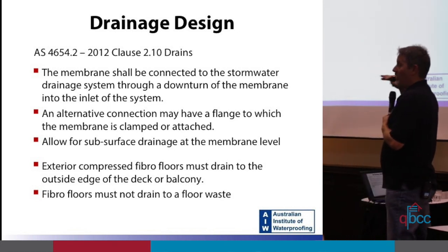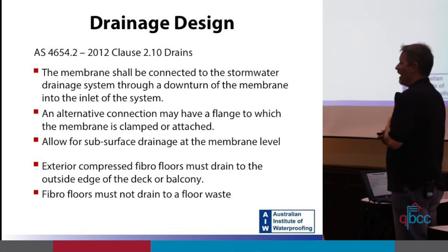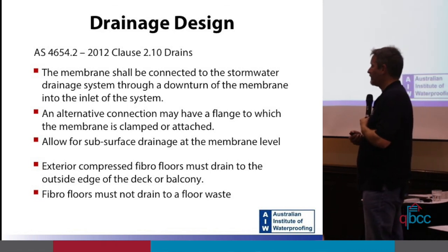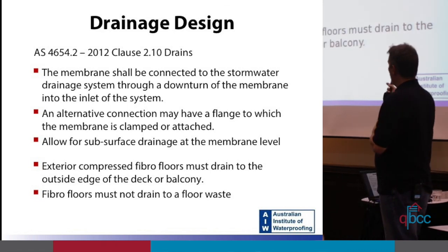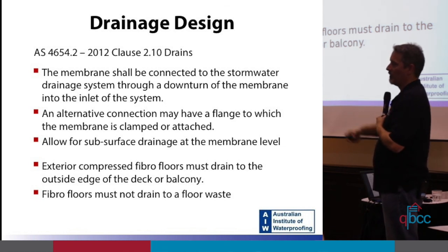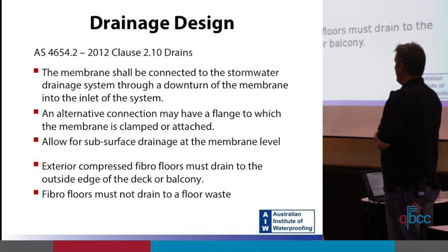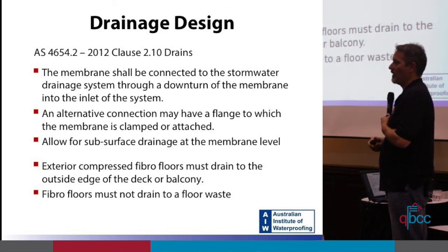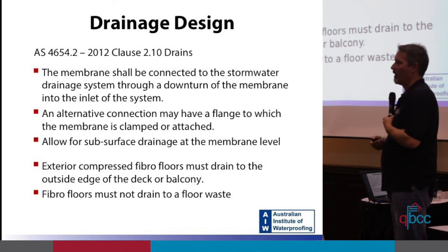And the whole idea is you need to allow for subsurface drainage at the membrane level. All right. And you'll hear me talk about this quite a bit more during this presentation. So subsurface drainage at the membrane level. For exterior compressed fibro decks like Skyon, your BGC board or Durafloor, they must always drain to the outside edge of the balcony. Right? That's not from the standard, that's from the manufacturer's installation manuals. So anything CFC based has to drain to the outside edge. They cannot drain to a floor waste in the centre of the deck.